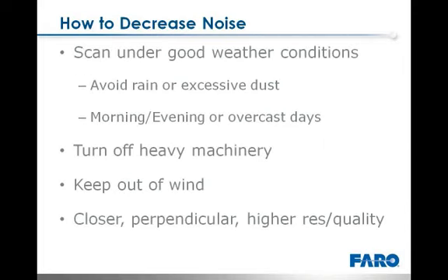The best way to avoid noise is to avoid getting it in the first place. Some of the environmental factors we just discussed can be alleviated while scanning, or at least improved upon. Try to scan when there is less dust or moisture in the air, and try to scan under less bright conditions if it's possible, by scanning in the morning or in the evening or on a more overcast day. For vibration, try to be careful when setting up the scanner. Turn off any heavy machinery around and try to keep it out of the wind.